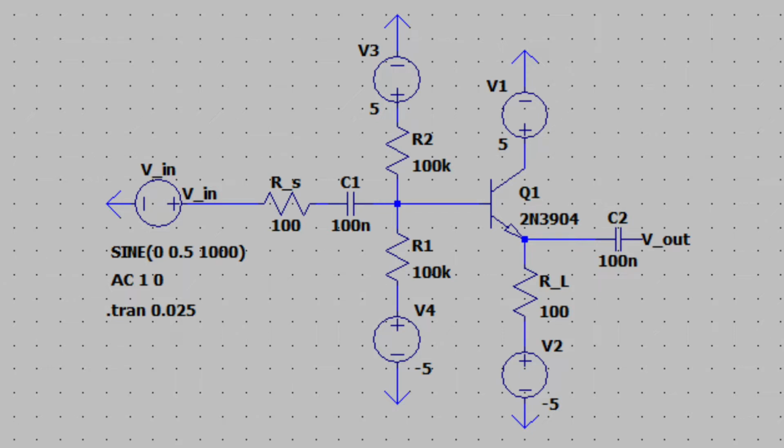After doing the calculations for Gm and determining it was 990 mS, and knowing the resistance at the load was equal to 100 ohms, we could rearrange the equation I had just stated previously to solve for the internal resistance, which I determined to be equal to or larger than 1000 ohms.